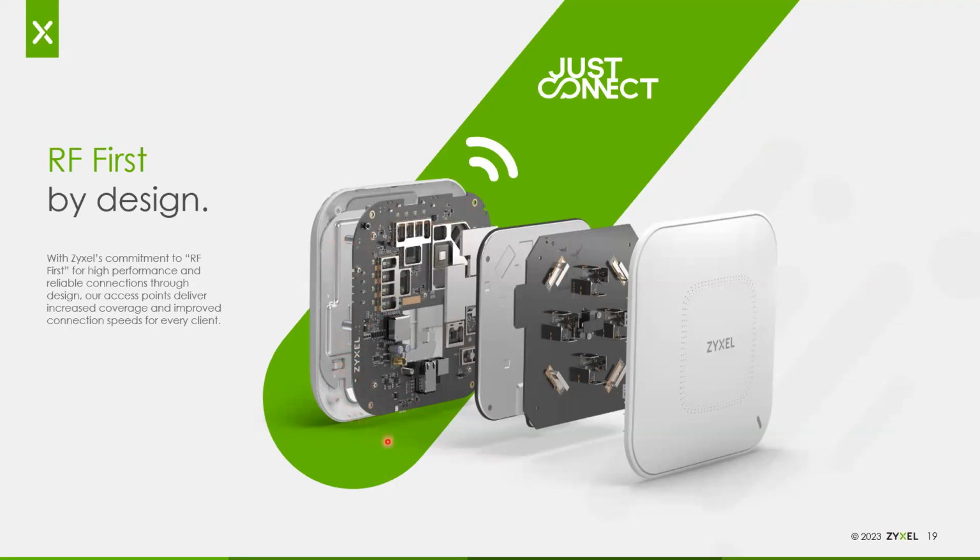So what we've done on all of our access points is we've got a large metal heat sink that goes behind the main board that's designed to draw heat off of the board. And then we've got lots and lots of vent holes. You'll notice some of our competitors that don't have a lifetime warranty often have no vent holes at all. And that's part of the reason why they fail early and why they can't offer the lifetime warranty, because due to heat issues, they will eventually fail. The other thing we do to prolong the life of our access points is we do not use any electrolytic capacitors. All of our capacitors are solid state.